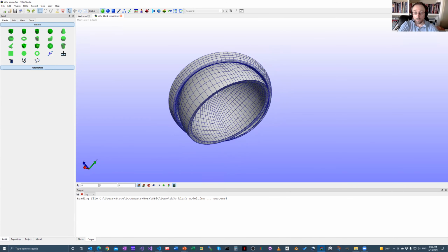There's a few different categories that you can choose the materials from. They are related to the different kinds of physics that you might be interested in simulating. For the mechanics case, we're only interested in either elastic and uncoupled elastic. I know there's already been a question regarding that, so we'll make sure to address that later in the webinar. But to keep things simple, we're going to start with an elastic material, and we're just going to pick a neo-Hookean. There we go. So we click OK to add that material to our model tree.